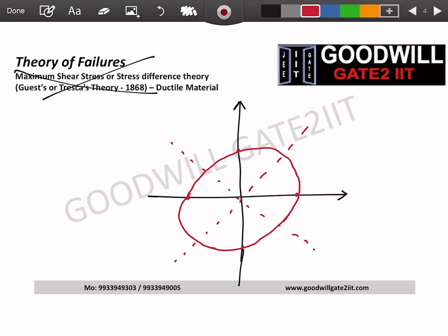Now, you will feel good. Let me finish this explanation. Believe me, I think after 5 minutes, you will be okay and good with this. And Mira, I hope this will answer your question even better. If you try to convert your sigma y into tau y at an angle of 45, this ratio will be 0.577. This was 0.5 for Tresca. This is 0.57 for von Mises.